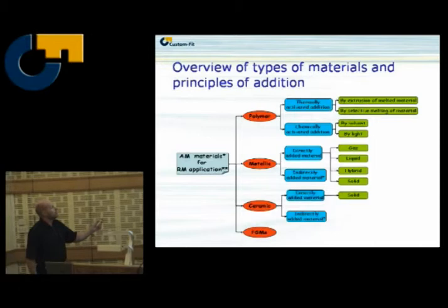Metallic materials can be added directly or indirectly. If it's indirectly, that is when you have made a sort of mold by additive manufacturing and then later use that mold to cast, but that's really costly, so I won't get into that here. The material properties will be as-cast properties in that case. If you use